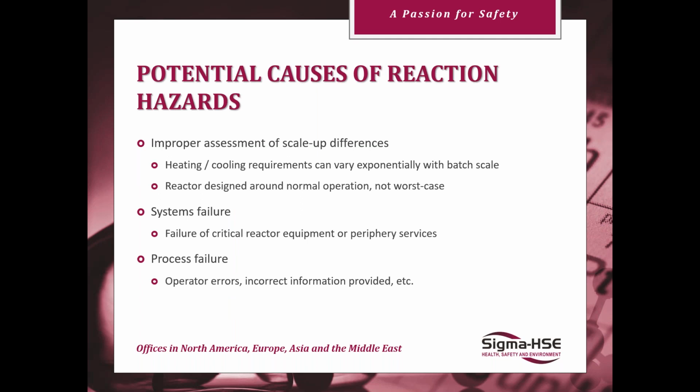So we're on to now potential causes of reaction hazards. Again, like we've just been going through, improper assessment of scale-up differences. Heating and cooling requirements can vary exponentially with batch scale. A reactor can be designed around normal operation, not worst case. So this can come into the safer envelope of operation that we were just talking about.